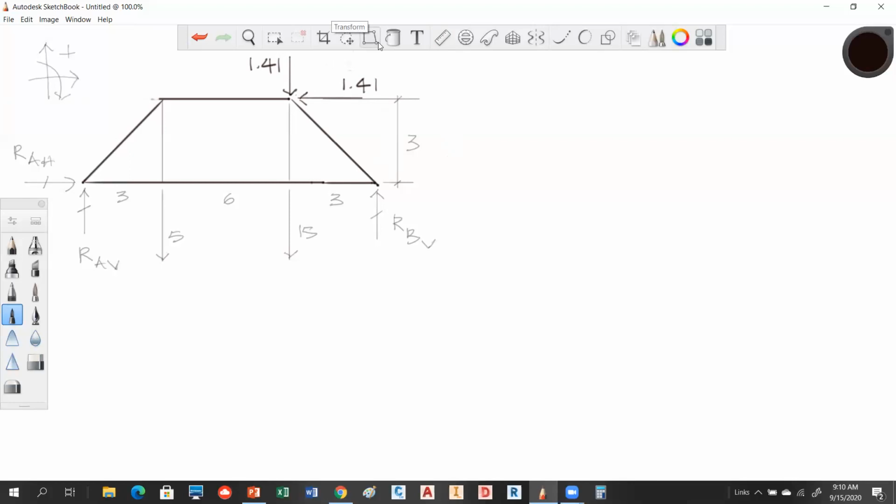All right. So anytime, and I'll say this again, anytime that you have vectors that are not horizontal or vertical, your first step, probably even before modeling reactions, get rid of those vectors. Break them down to their components so that when you get into doing your moment equation, your moments are going to smoothly solve. Otherwise, it becomes a real mess, okay?